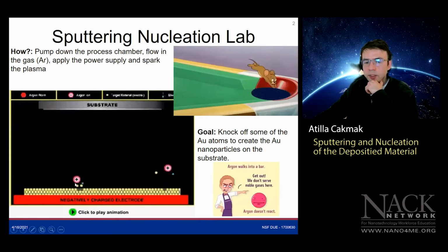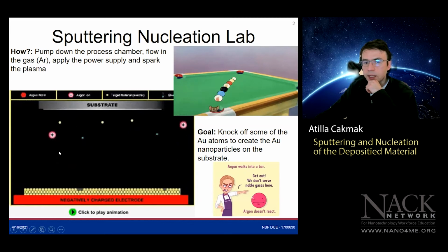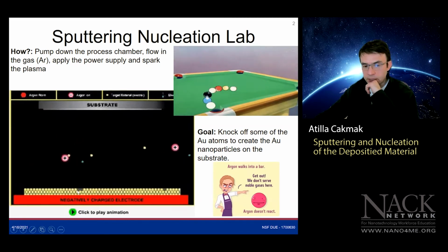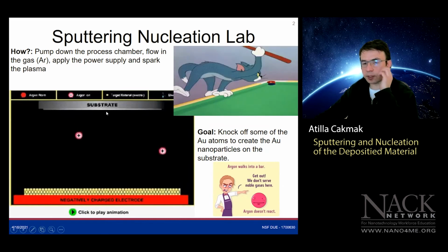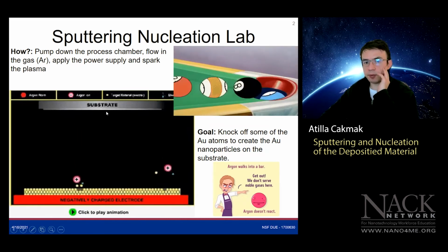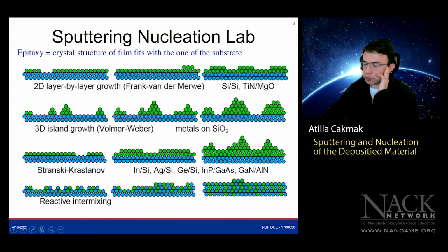As we were saying, with the sputtering, we're generating the plasma, we're attacking the target with the ion, and then we're knocking off some particles, and those are going to the substrate with the help of diffusion. And what Rich is going to show us is a gold sputtering deposition, but we're going to do it for an extreme case. We're going to do it for a very, very short time, okay? For like 10 seconds or less.